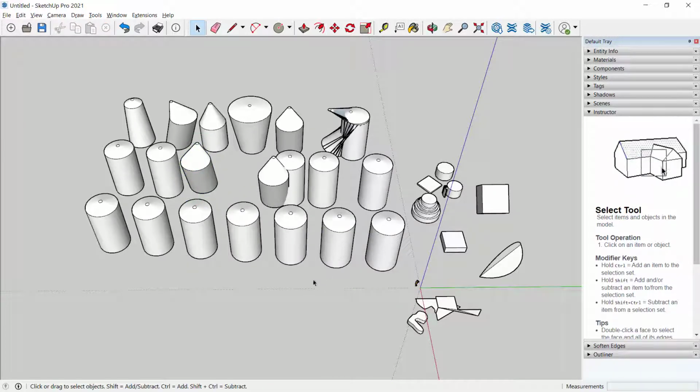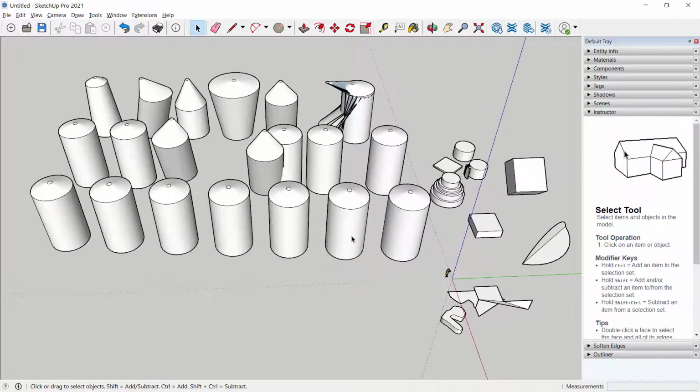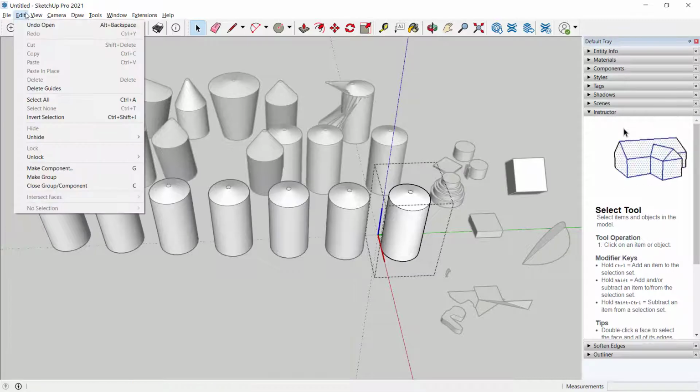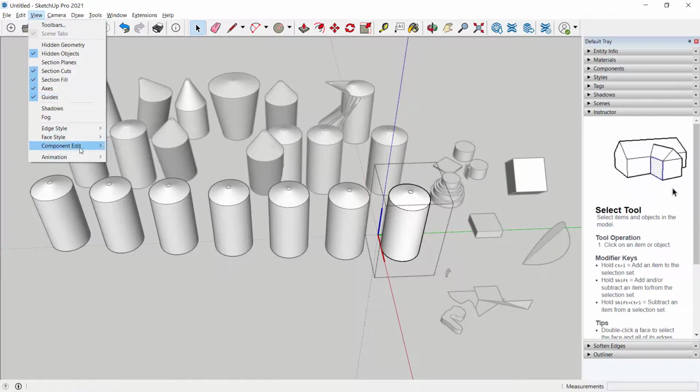Now, the final model option is the component option. And for that one, when you edit one, they all will change. And you see how the rest of my model has gotten grayed out, but slightly less grayed are these other components. And in fact, while I'm editing a component, I can hide the rest of the model or hide similar components.